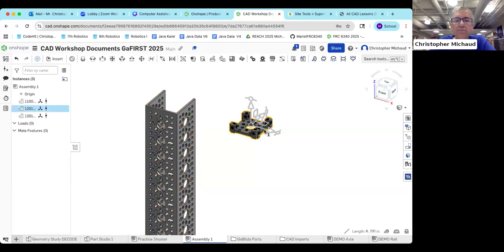Clicking the quad block one time, there are these move and rotate handles. If I use the arrows, that allows me to sort of slide the piece along your X, Y, and Z axis. The circles with the little lines in them, these are your rotate handles. I can grab and rotate. I'm going to type 180 and press enter. And that rotates it to the right orientation. You don't have to when using constraint parts, but I find it's easier when you're putting things together if they're close to the proper orientation before you start.